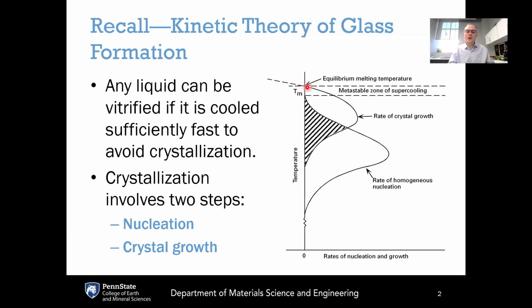At temperatures below the melting point, we develop a similar type of trade-off between thermodynamic and kinetic effects as compared to what we get with nucleation. As we lower the temperature below the melting temperature, there's a greater thermodynamic driving force for crystal growth to occur because there is a greater lowering of the Gibbs free energy after undergoing the phase change from the liquid state to the crystal state. Then we go through a peak. That peak occurs at the temperature where there is an ideal trade-off between thermodynamic and kinetic effects for crystal growth. And at temperatures below that peak, we are kinetically controlled because of the exponentially slower kinetics of taking atoms or molecules from the liquid state, crossing that boundary between the crystal and the liquid, and getting them incorporated into the crystal state.